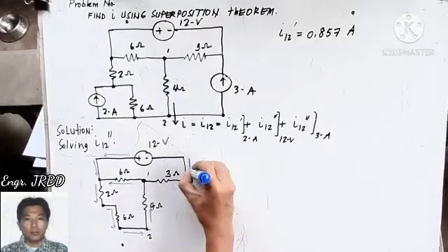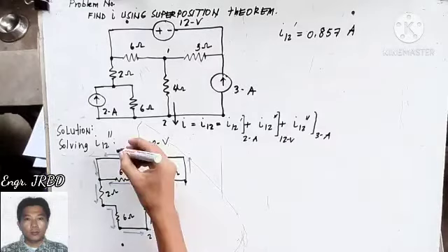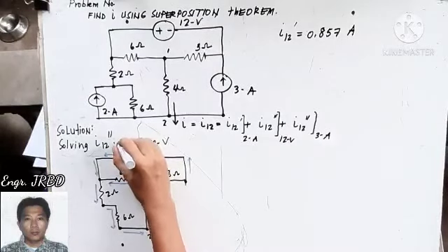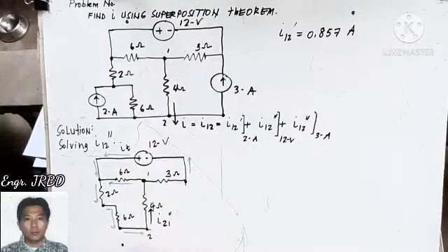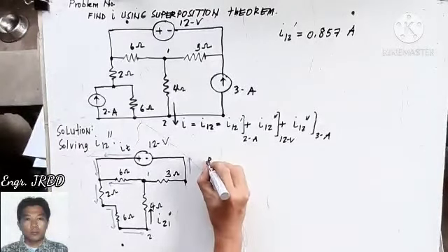This is also your total current. So the current into your 4 ohms is a current that is coming from terminal 2 and terminating in terminal 1. So this is your I21 double prime. Okay, what is I21 double prime? We need to obtain first the total current. Total current by Ohm's law?